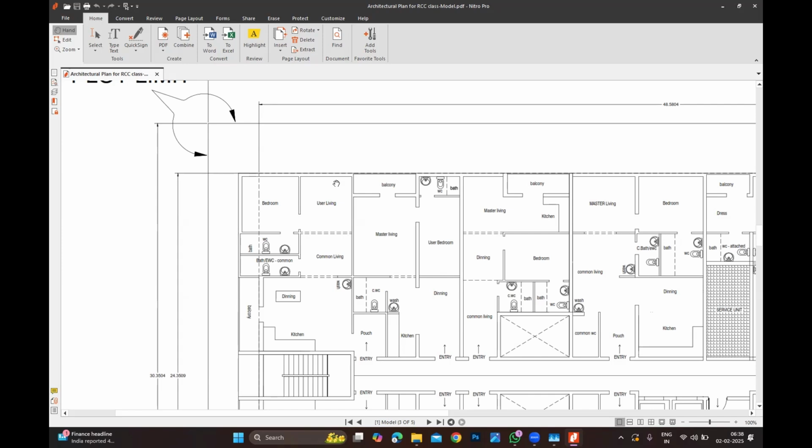You understand. Some of the time, I'm getting the column size or wall thickness a little bigger. Say instead of 300 millimeters, I keep 350 millimeters. Then my reinforcement is drastically reduced. Instead of demanding 20 millimeter dia, only 16 millimeter dia is required. So I'm telling you, do it. But this has to come from the concept design.